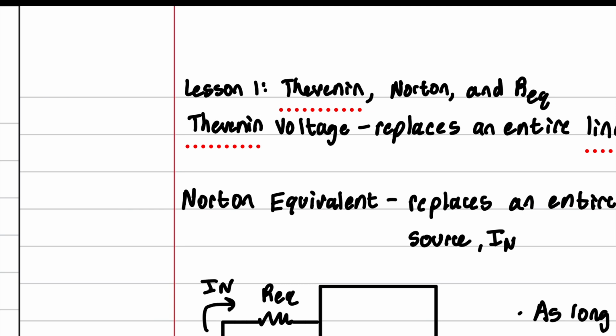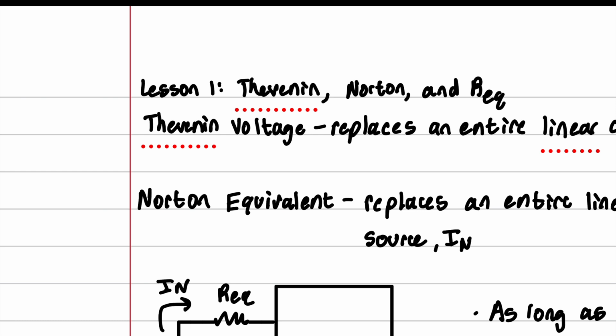Basically, this person named Thevenin, I don't really know anything about him, but he said that if you have two networks, and one of the networks has resistors and current sources and basically linear devices, then you can simplify it down to one resistor, which is R equivalent, which we learned ways to find in the last unit, and a Thevenin voltage.